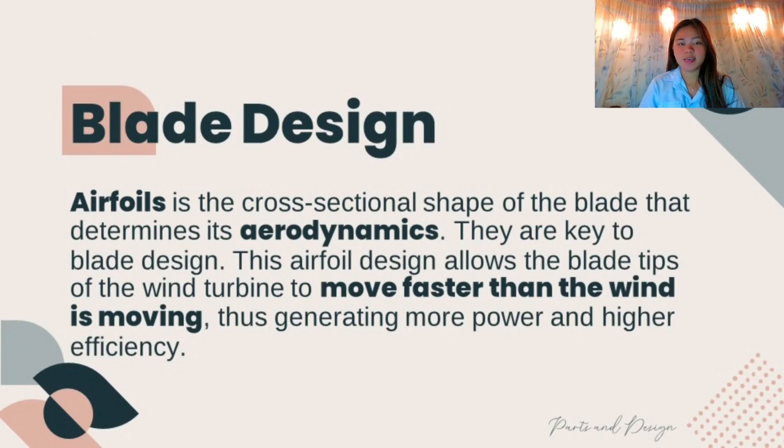Blade design. Airfoils is the cross-sectional shape of the blade that determines its aerodynamics. They are key to blade design. These airfoil designs allows the blade tips of the wind turbine to move faster than the wind is moving, thus generating more power and higher efficiency.